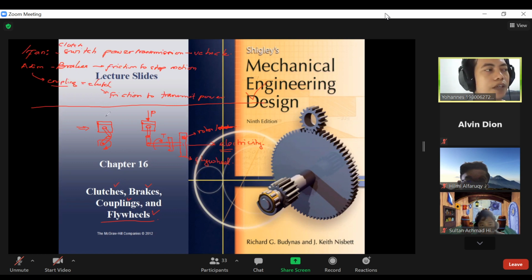Because we know that the explosion here is intermittent, not continuously working. If you see the time history, the explosion happens and produces positive pressure and gives the output torque. But then when the piston is in suction mode, it will require pressure, so it works in negative pressure. And then the cycle repeats between giving the output and requiring the input power.